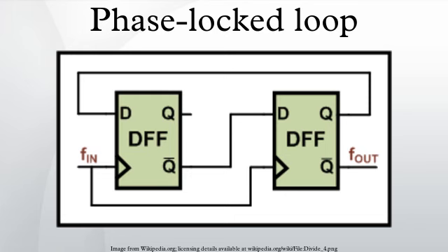The VCO frequency is usually taken as a function of the VCO input as ω2(t) = ω2free + g_v·g(t), where g_v is the sensitivity of the VCO and is expressed in Hertz per volt, and ω2free is the free-running frequency of the VCO. The loop filter can be described by a system of linear differential equations, where g(t) is an input of the filter, x is an output of the filter, A is an n by n matrix, and x0 represents an initial state of the filter. The star symbol is a conjugate transpose. Hence the following system describes the PLL, where θ0 is an initial phase shift.